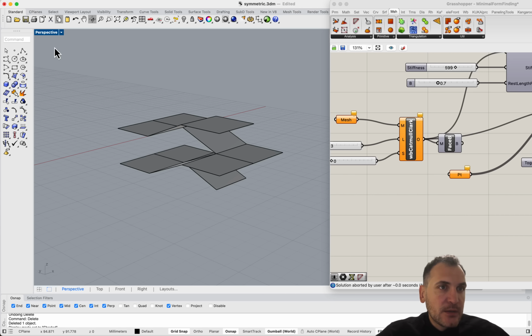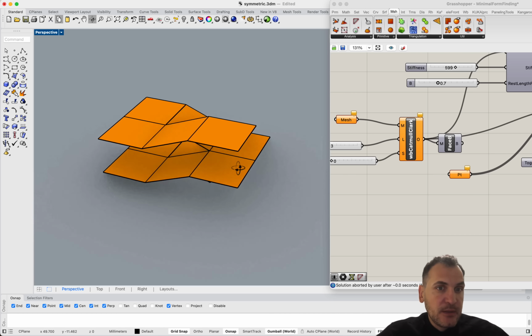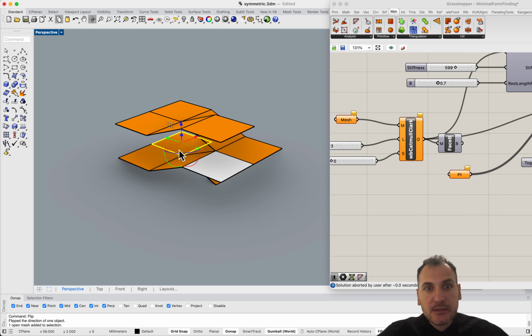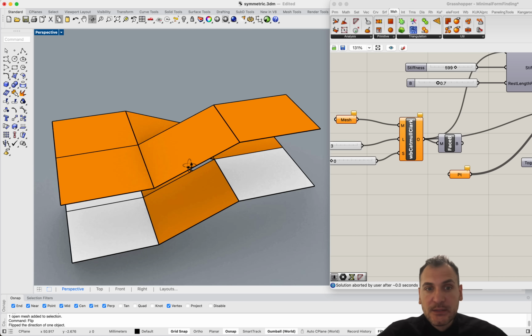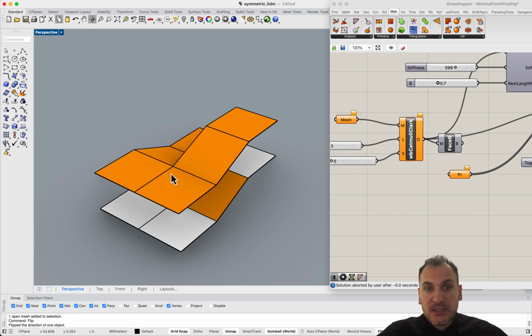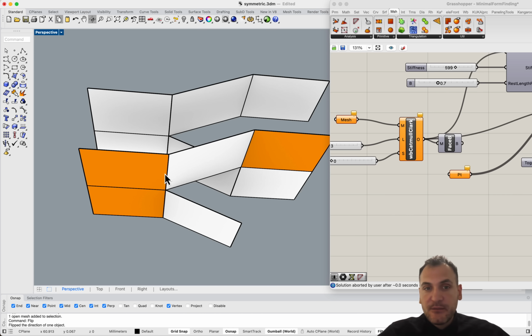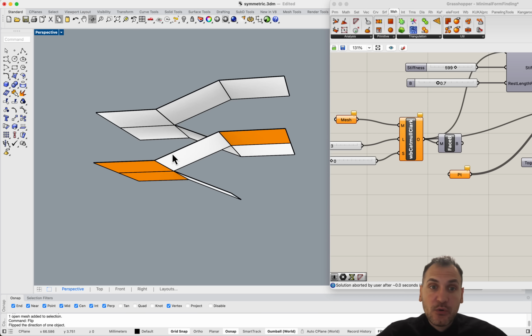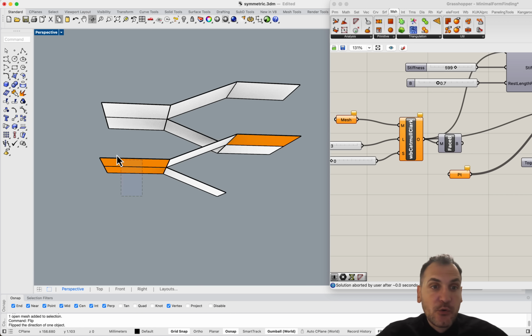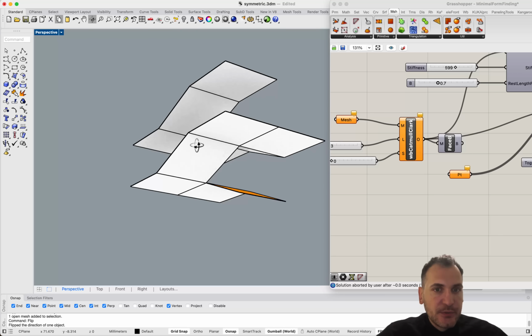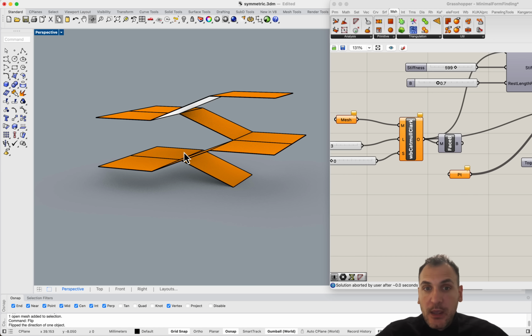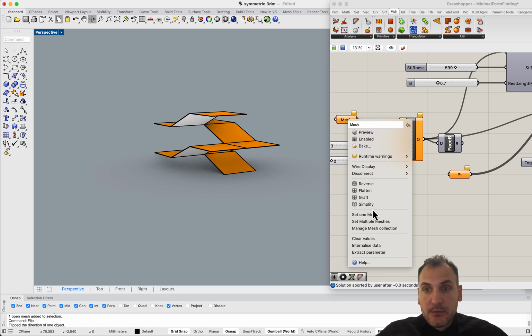And the other thing you want to watch out for is in the rendered view. Let's say some of these surfaces are facing in the opposite direction, right? That's why we want to visualize the back faces, because you want the surface normals in the facing direction to be the same. So if these are kind of flipped, that won't give you an accurate mesh, or it won't behave in the correct way in the simulation. So you want to flip these and make sure that you have a construction like this. And this could actually be used in the simulation too.